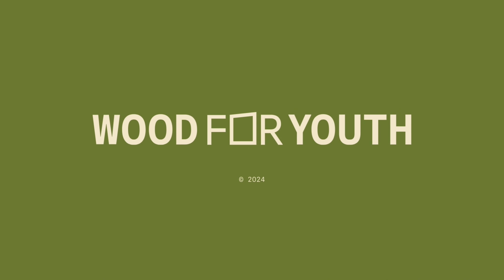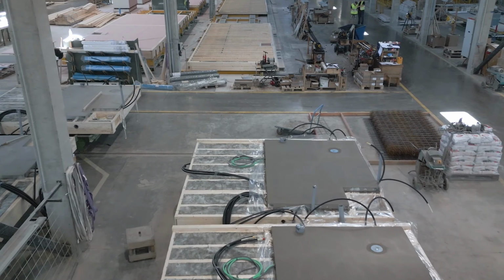After the floor framework is flipped, the next steps include installing any necessary plumbing into the structure and integrating a specific floor section for a wet room, if one is present, into its pre-prepared location in the structure. Many manufacturers assemble the wet room floor later, after the room element is completed.